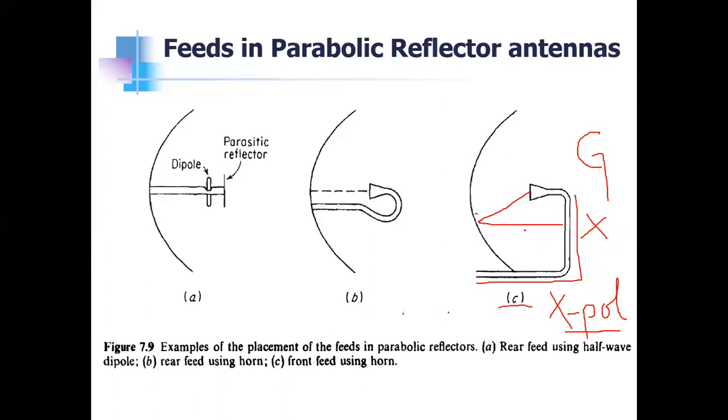So there could also be something else called impedance mismatch at the feed, and that is because some of this radiation re-enters the feed. So it could go like this, and then it could hit back the feed itself, and this is the mismatch. So the mismatch occurs between the antenna and the feed. Both aperture blockage and this mismatch due to reflection can be eliminated by not employing this design.